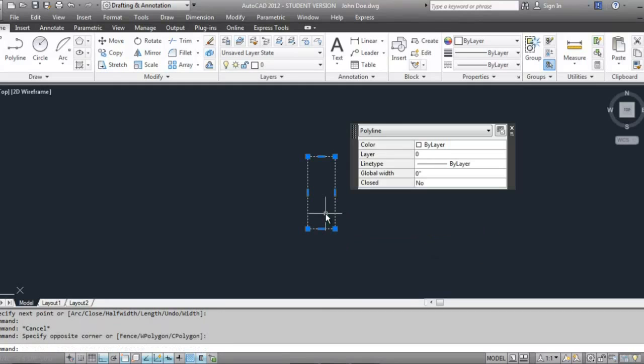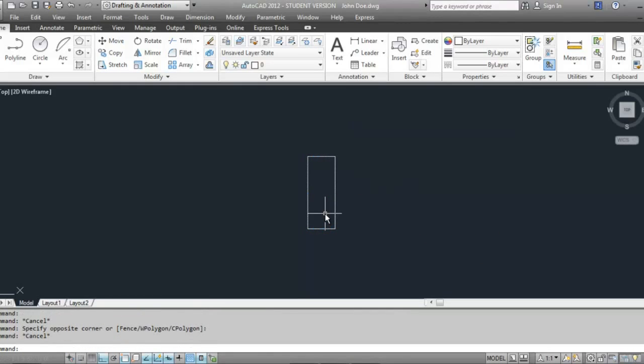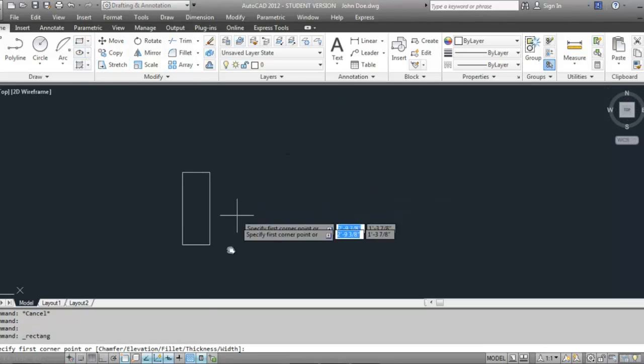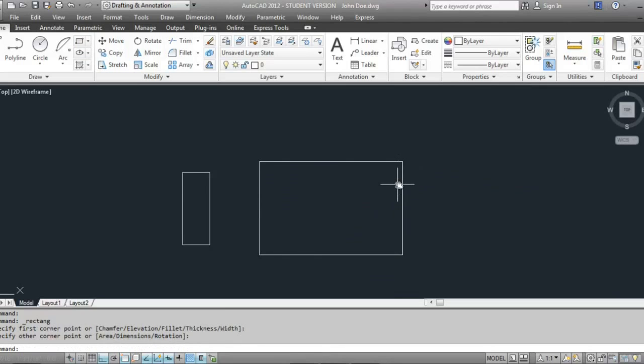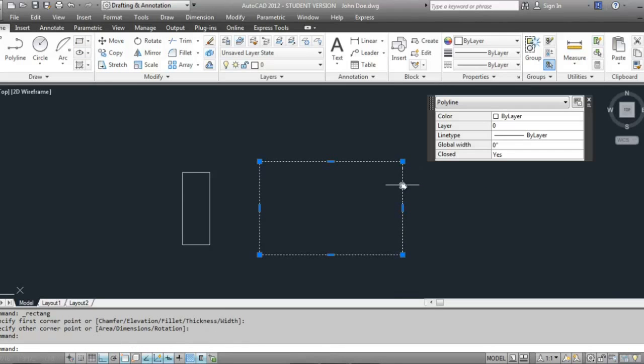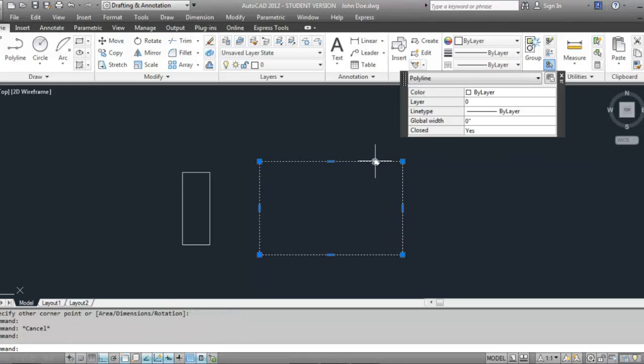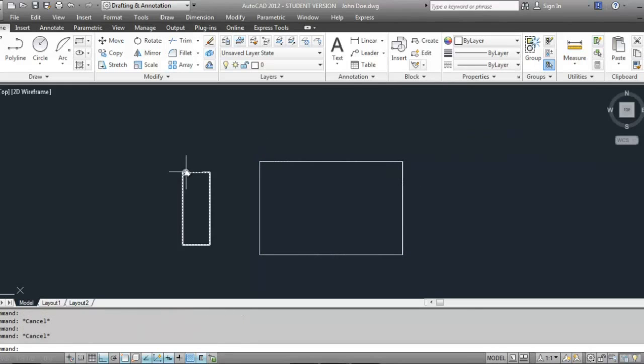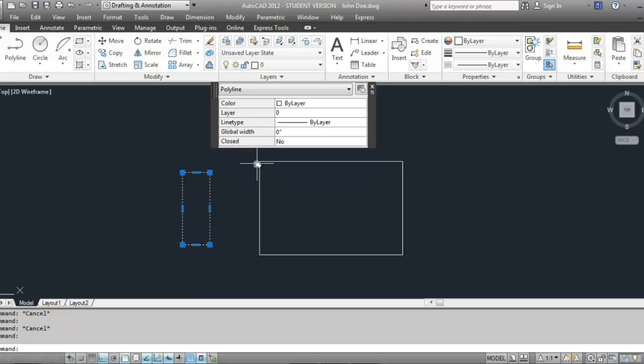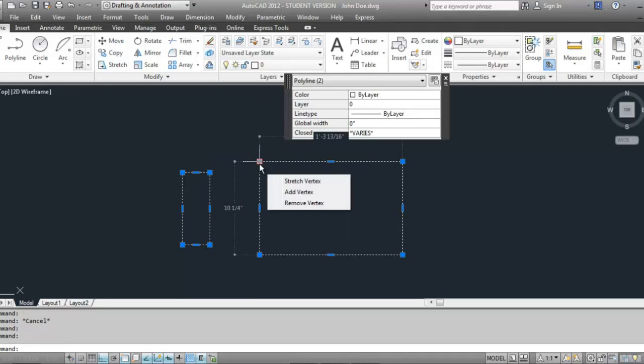Okay, so not much difference between the line and the polyline command in drawing, except when you're drawing something architectural or that is detailed, then you want everything to be connected and be a single entity, then you would use a polyline. Now a rectangle is also a similar concept. When I draw a rectangle and click on it, it is made up of polylines that make this rectangle. So when I click on a rectangle made by the rectangle command or a rectangle made using the polyline command, they both look the same. They're all connected 4 lines.